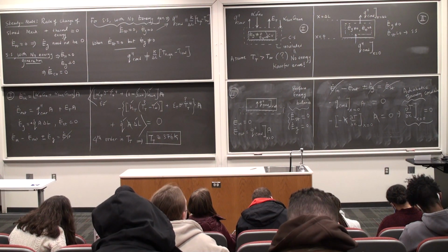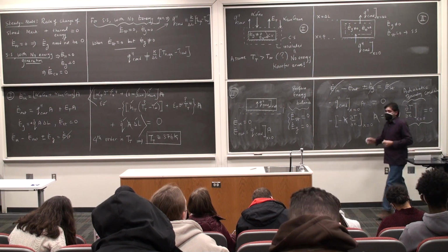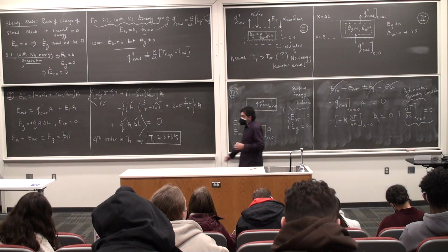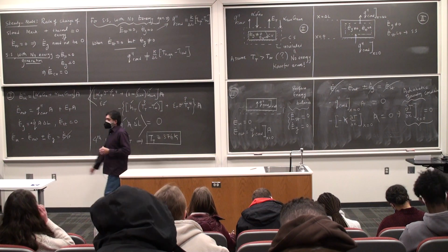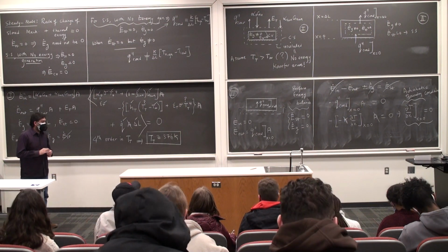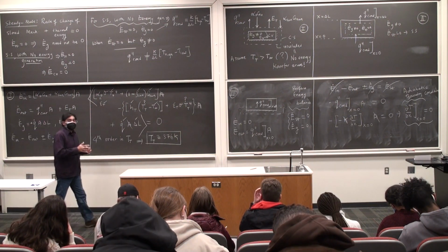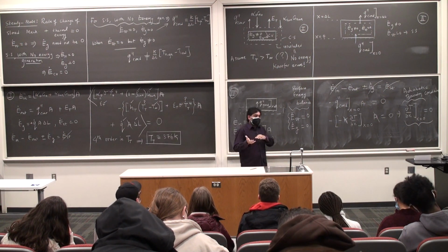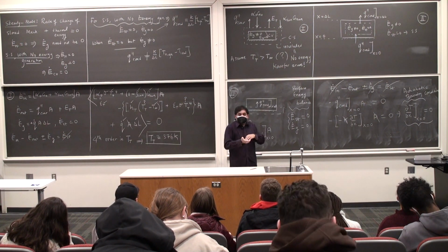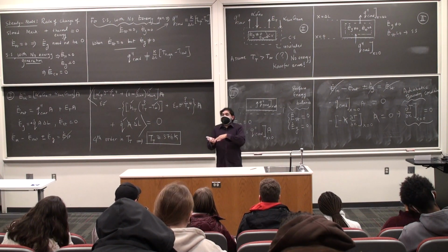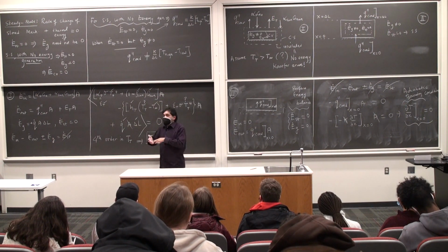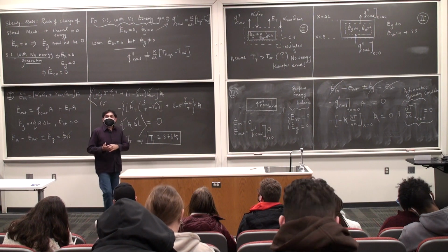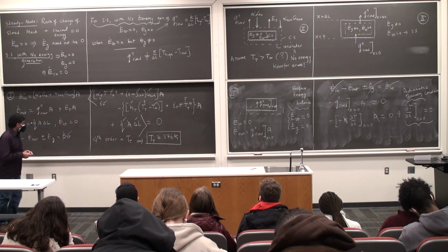And in mathematics, in partial differential equations, which is all heat transfer is about, this is called a Neumann boundary condition. You will have two types, Dirichlet and Neumann boundary conditions. The Dirichlet boundary conditions are boundary conditions for the temperature at that particular surface. If I take the first derivative with respect to space, I enter what is called a Neumann boundary condition. And we'll talk more about this on Monday. Okay?